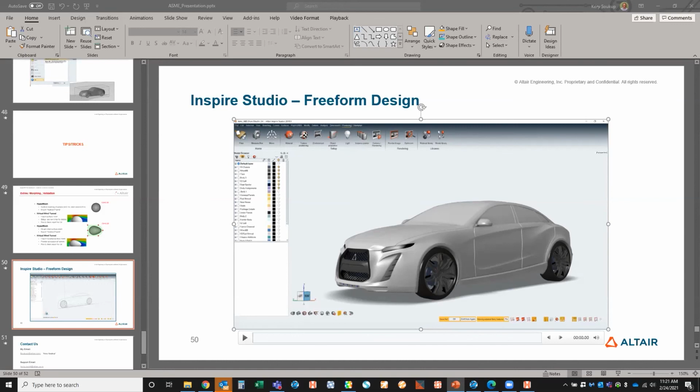Virtual Wind Tunnel is more or less just calculating the impact those vortices will have on your model itself. But it's a great way to generate quick initial concepts and start creating your iterations at the start. Once you get to your final design, you want to make sure that you run something in AccuSolve, for example.